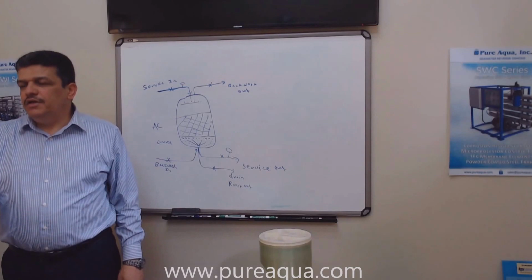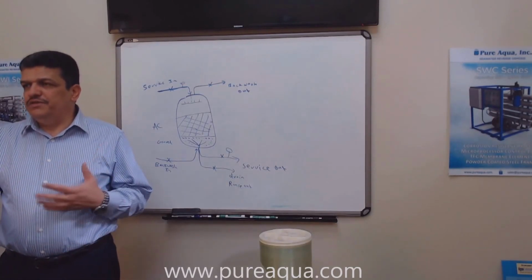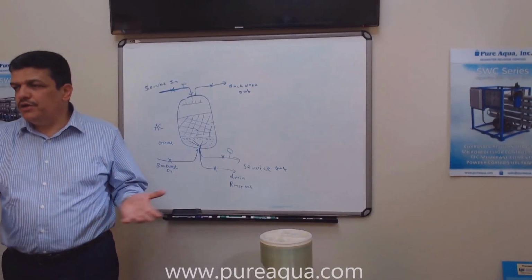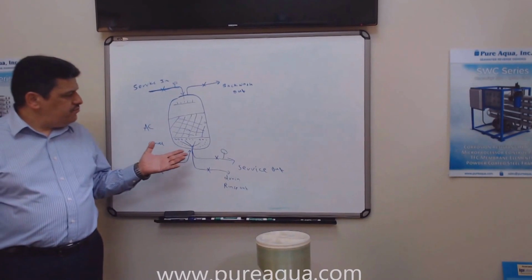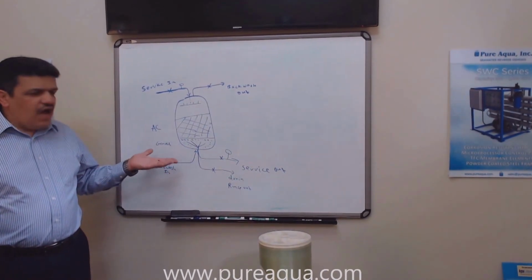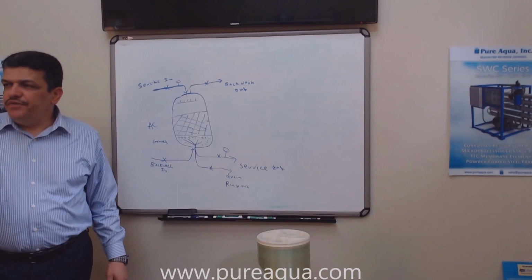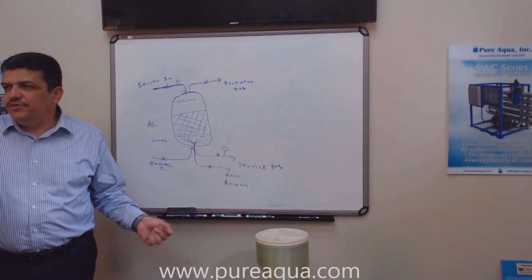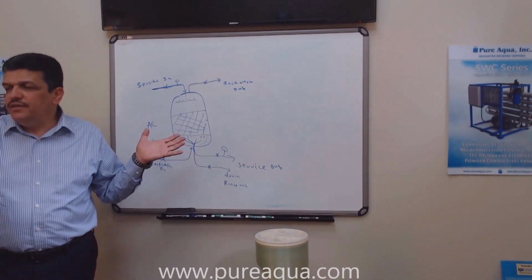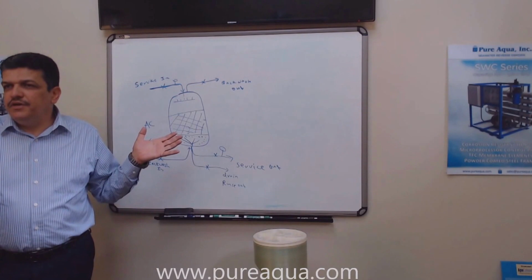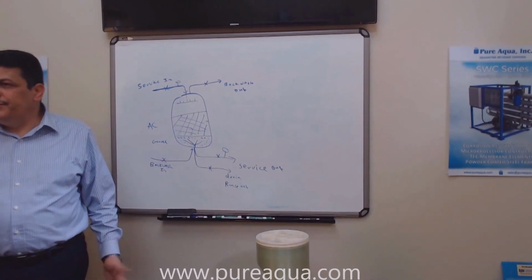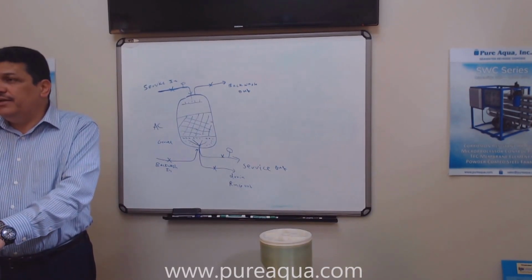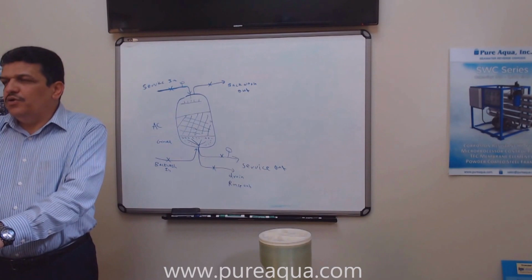The carbon filter is a good media for the specific things that we mentioned, like organics, chlorine, bad taste, smells, odor, and all those things. Now, how often do you want to backwash the carbon filter? It depends. Some people don't even have a media filter before that. If you are using the carbon filter to do both filtration and chlorine absorption at the same time, which I don't recommend, you need to backwash maybe once a week or twice a week.